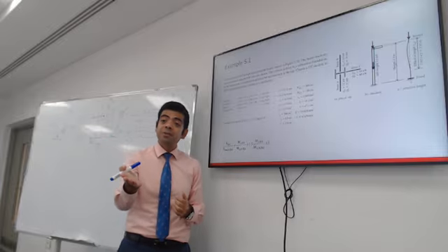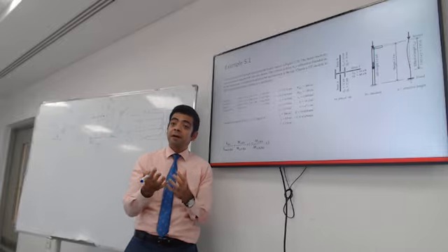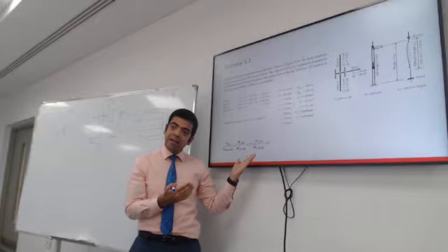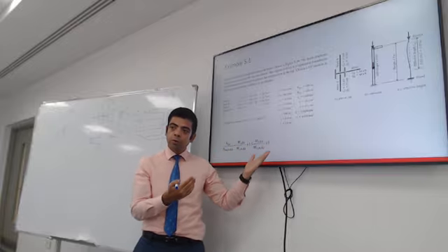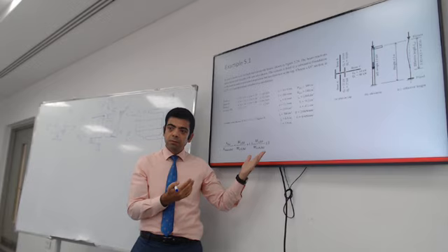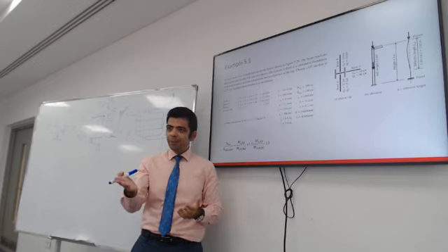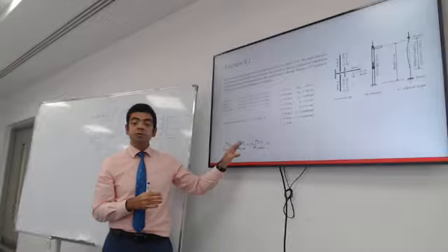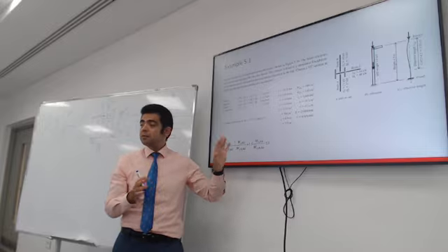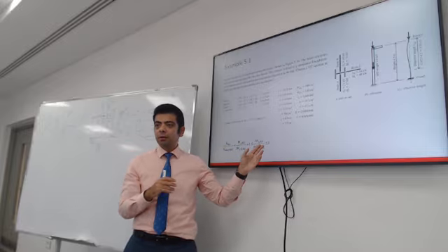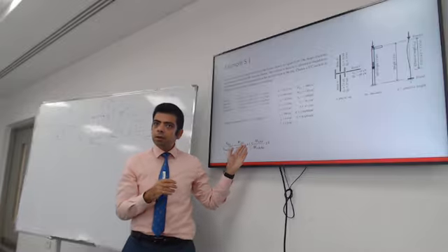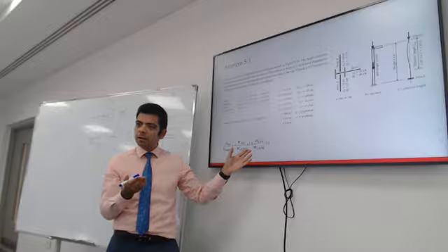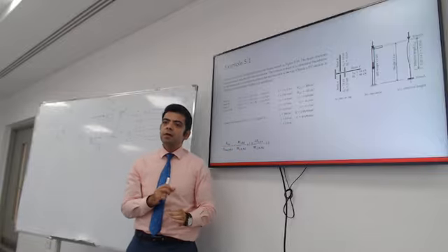So how would your section be effective? Do you want the stresses to be way less than 1 or closer to 1? Closer to 1. Yes. You choose a bigger section if the stresses are too high and it's more than 1. If it's very small, like 0.5, you're using 50% of the capacity, then this section is not very economic.